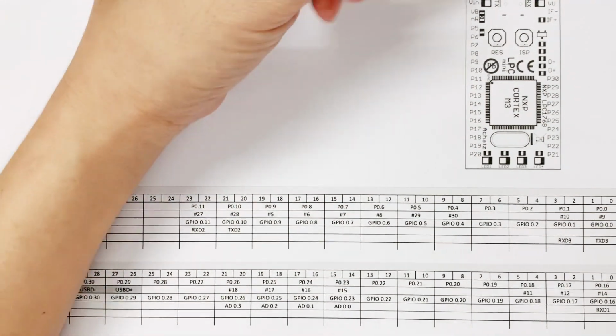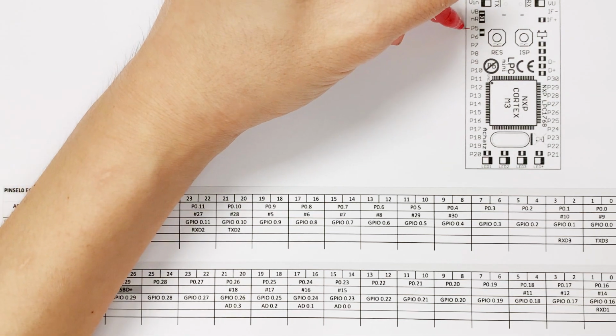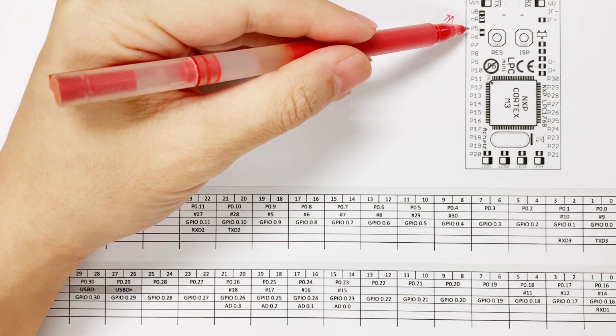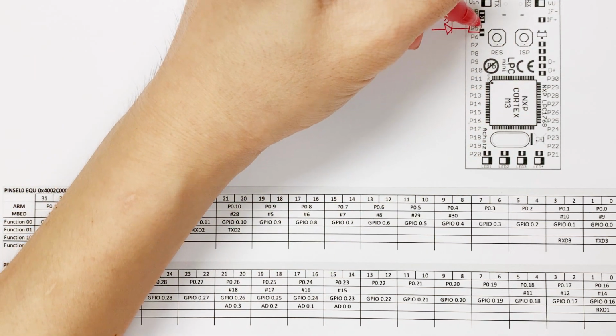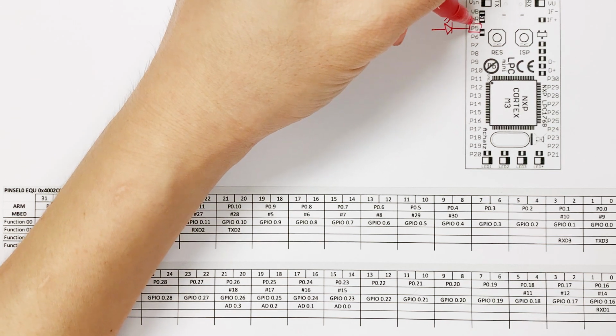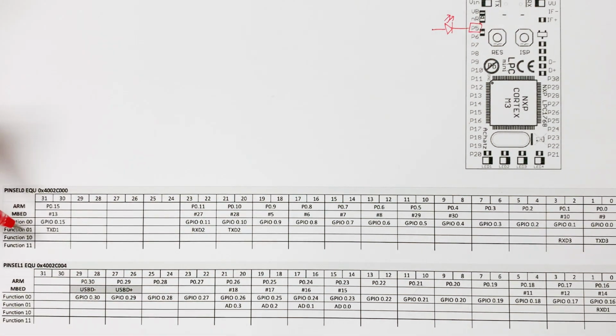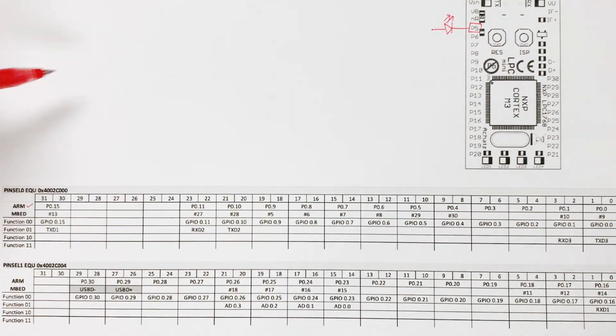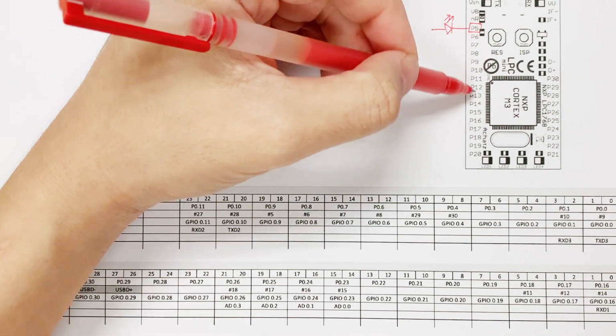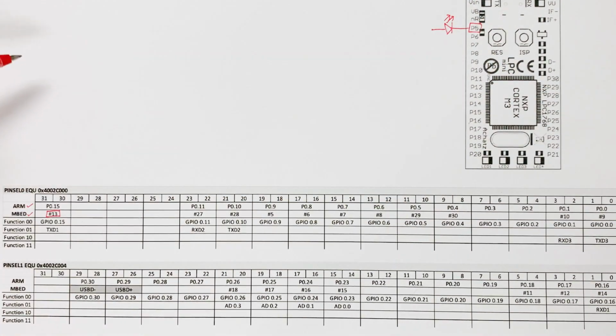The first thing we need to do is, for example, if I decide to connect an LED to pin 5 on the mbed module, I need to figure out which port or pin this P5 represents. If I refer to the table, there is a row of values for ARM, which is what we have learned previously, port 0.15, port 0.11 and so on. And there's also a row of data for the mbed. The number on the mbed row represents the P numbers that mbed provides for us.